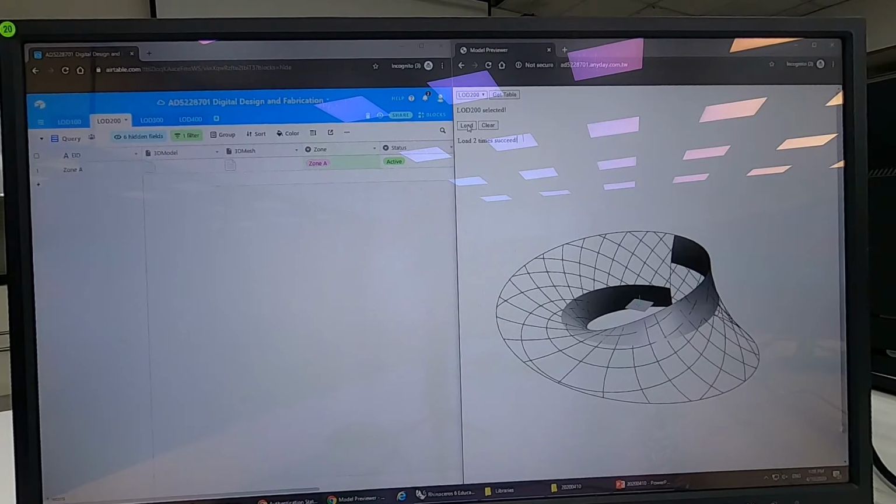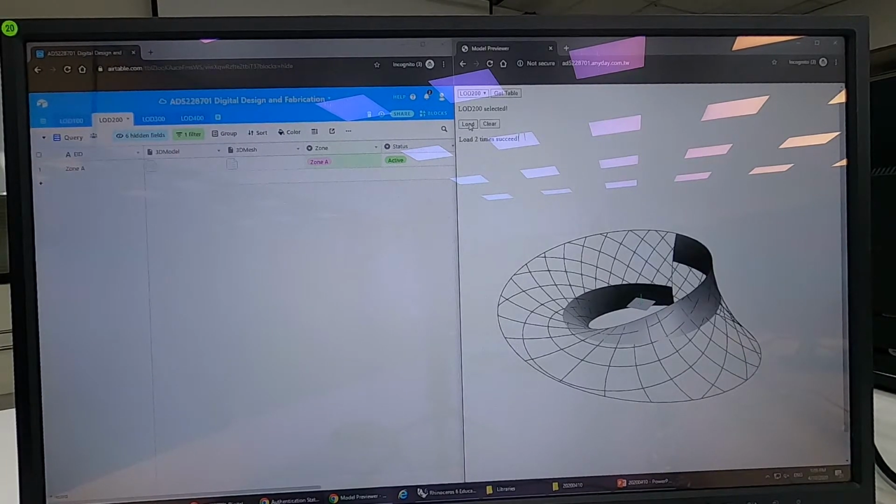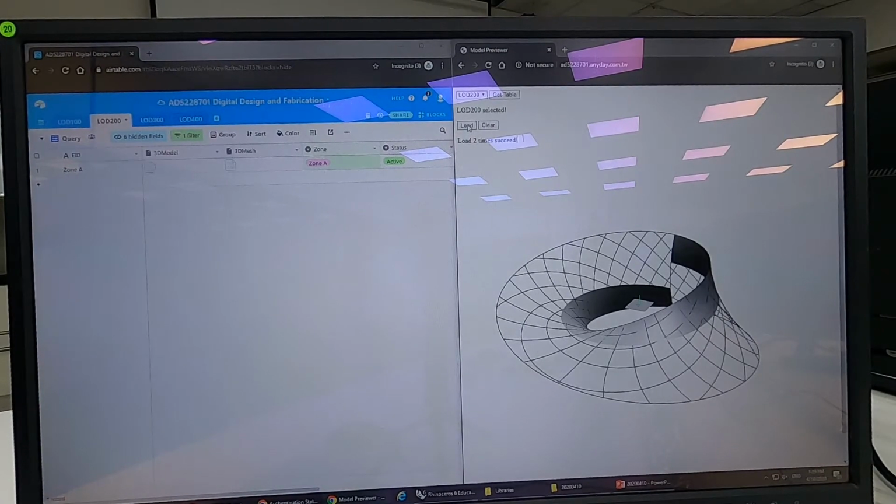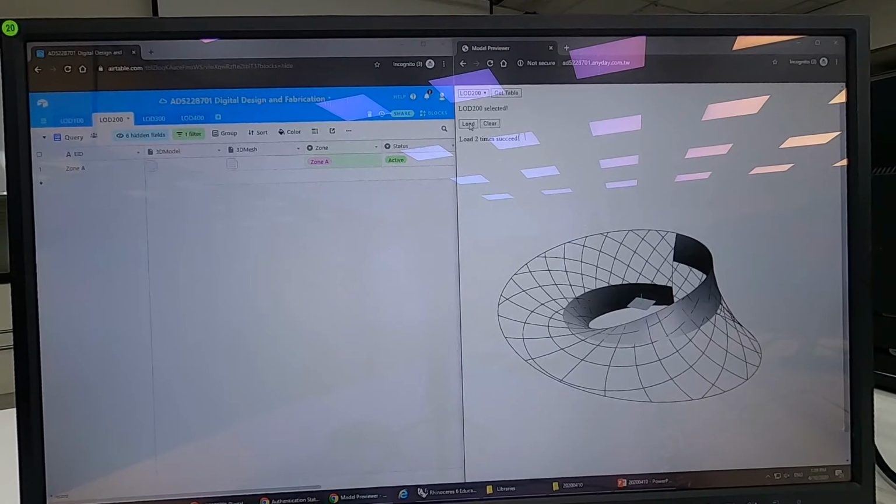The detailed or very clear definition of 100, 200, 300 can be project dependent, which means the standard might not be universal. A small project is slightly different from a larger project and can be very different from a huge project. So LOD 100 corresponds to the most abstract level of the building, which means we regard the entire structure as one single element.